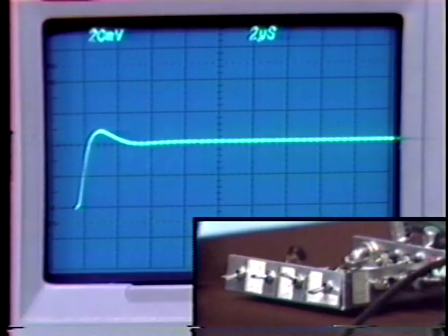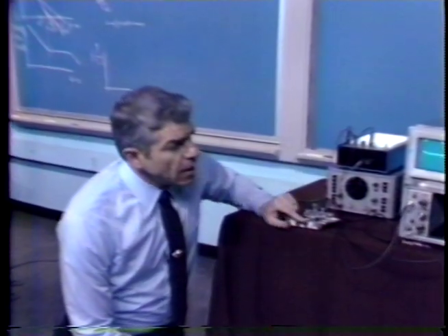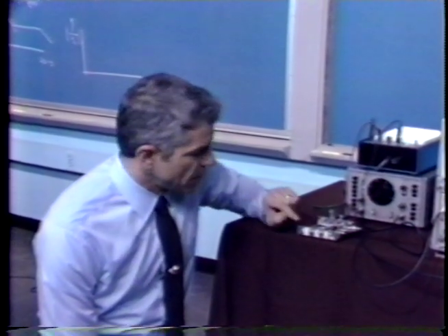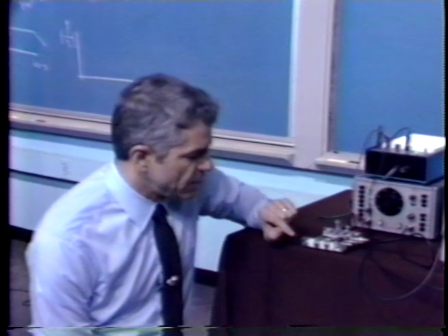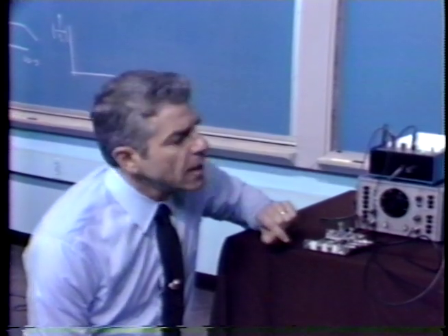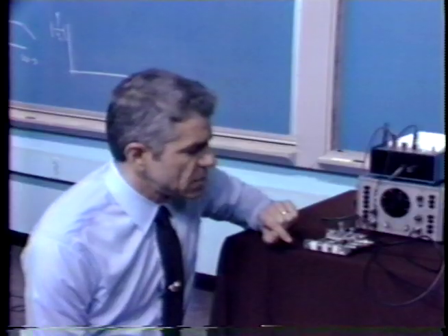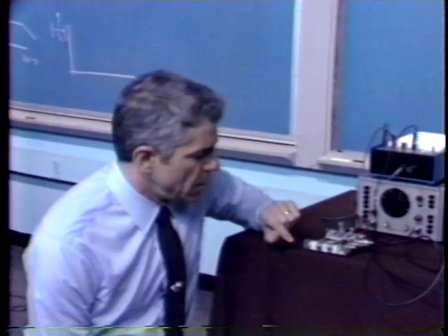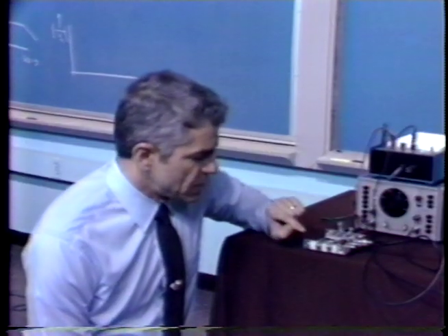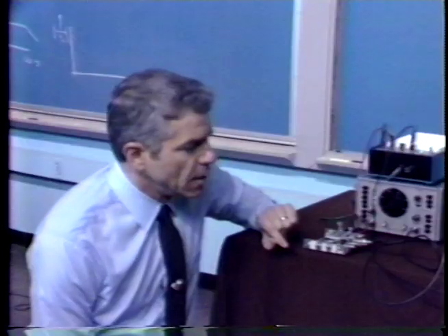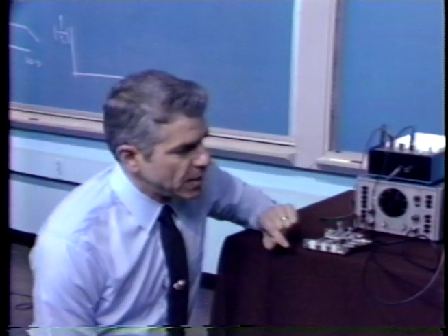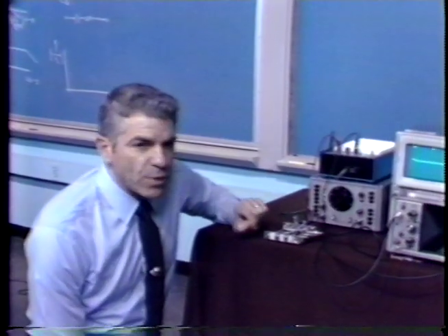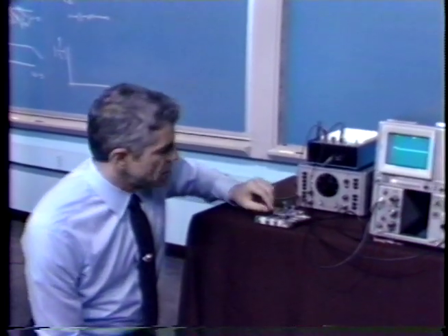What's the difficulty with this kind of compensation? Well, one of the things is it's very, very special purpose. We have already looked at 1 over s squared compensation and found out that it was somewhat special purpose. Here we're tailoring compensation to a specific load, in particular a capacitive load, and we're choosing the zero associated with this form of compensation to bear some relationship to the pole caused by the capacitive load. What happens if we take the capacitive load away? Well, the system goes unstable.